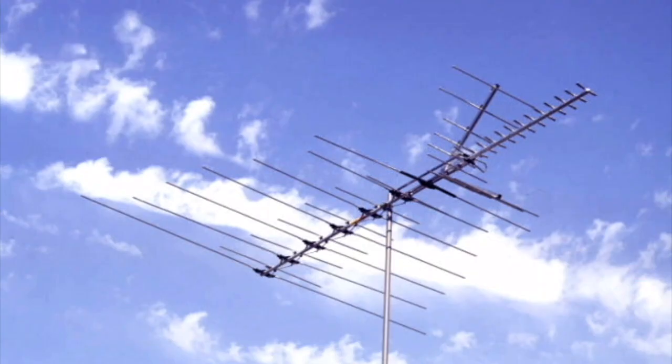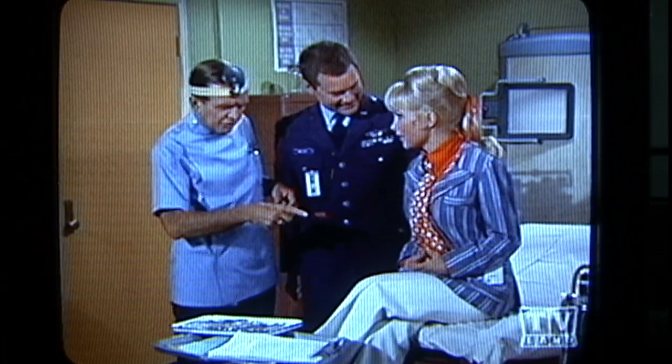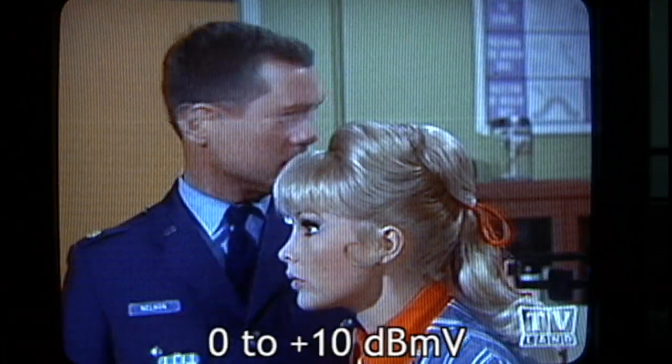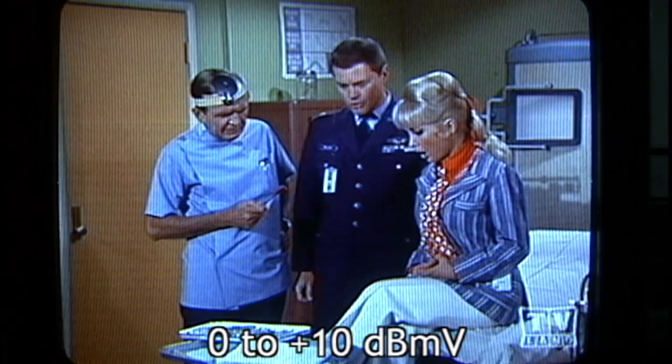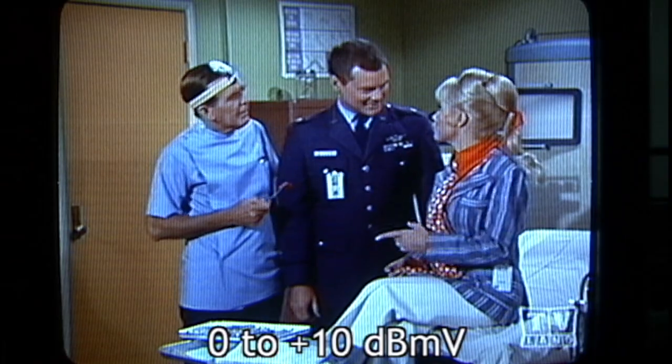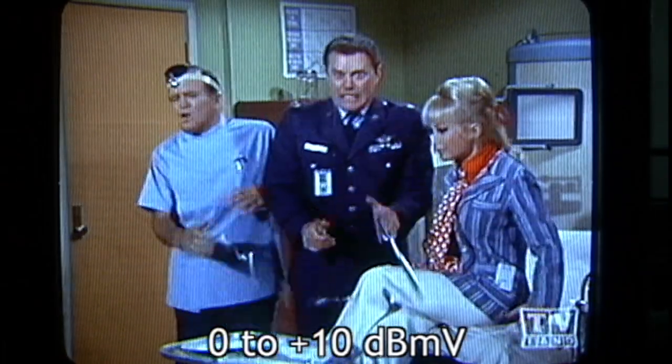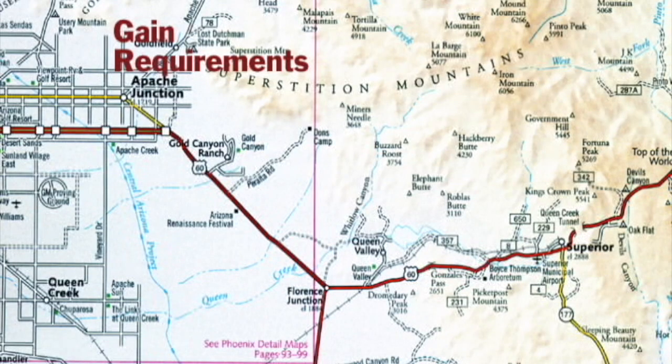To receive a good quality, noise-free picture, the antenna needs to deliver a signal level of 0 dBmV to the receiver, similar to a cable signal, although most receivers will give an acceptable picture down to about -10 dBmV. To deliver this signal level, the antenna requires a certain gain.